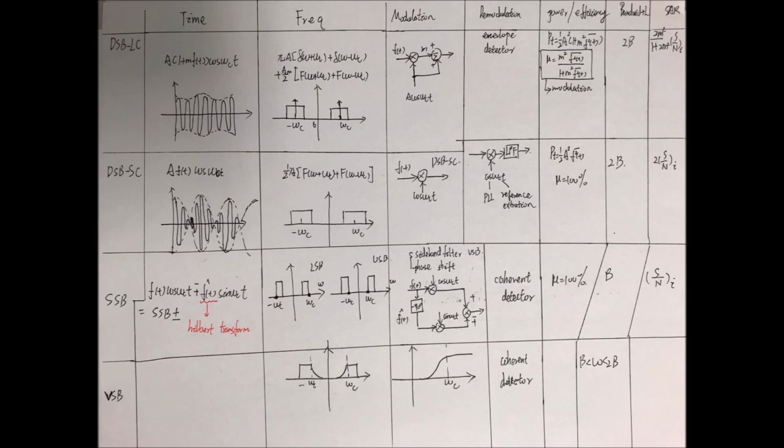In order to find a perfect reference signal to mix with your received signal, we need to use a phase lock loop for the phase and frequency reference, right? For frequency. So for this one, my receiver is much more complicated compared with double sideband large carrier.